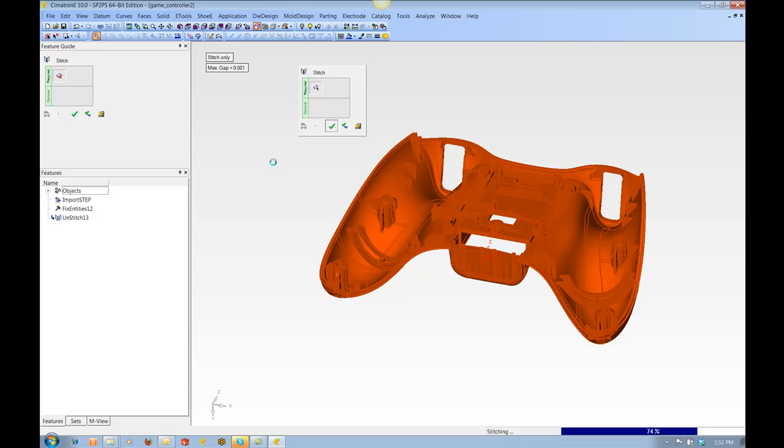This is actually pretty uncommon too. Like I said, I don't normally use check and fix entities, but I could tell it was taking a long time when it was interrogating the solid body, so I immediately suspected something was wrong. If this doesn't fix the problem, we may try translating it differently.